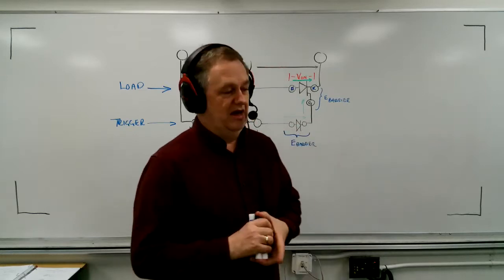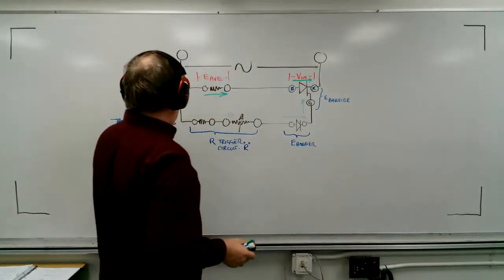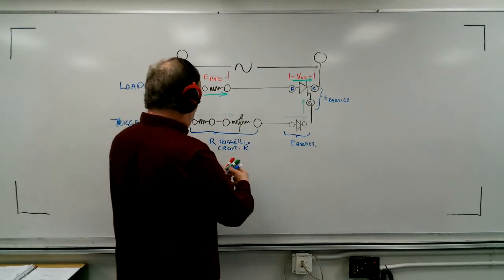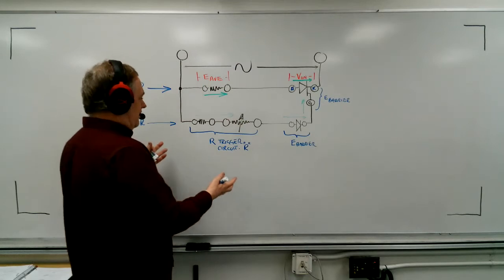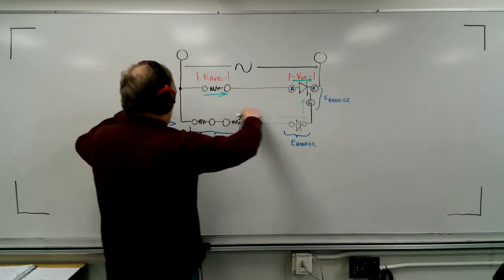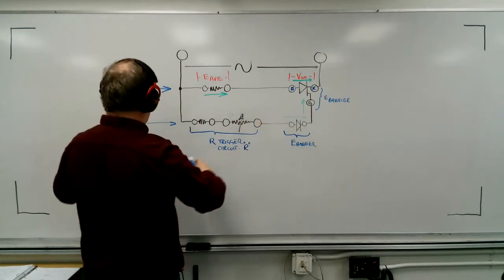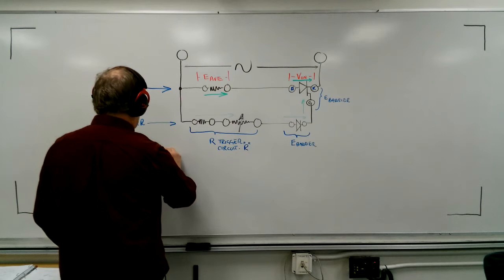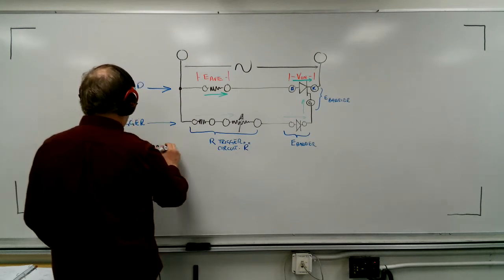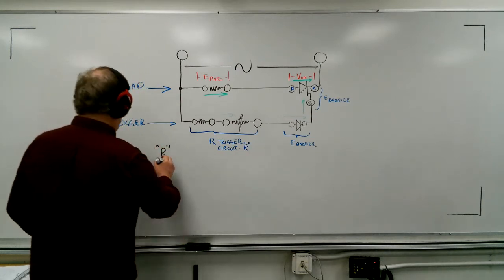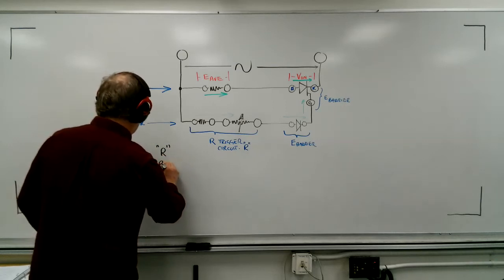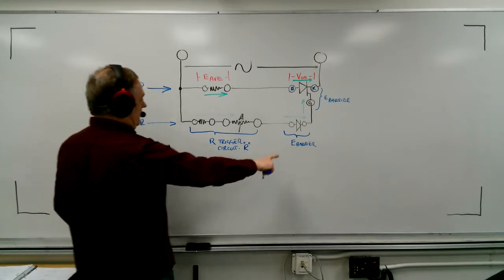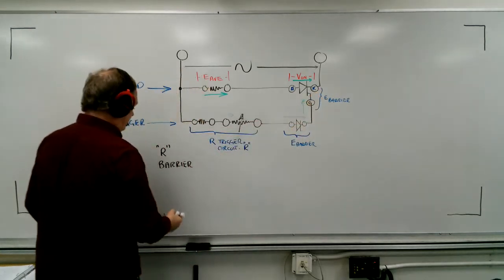So just keep an eye on that, okay? When it comes to this, what is it that we need? What are the parts, the formulas and things that we need to basically solve our trigger circuits? Well, we need to know the resistance values. We need to check barrier voltages, and that includes a diode if we have one, and the gate voltage, okay?